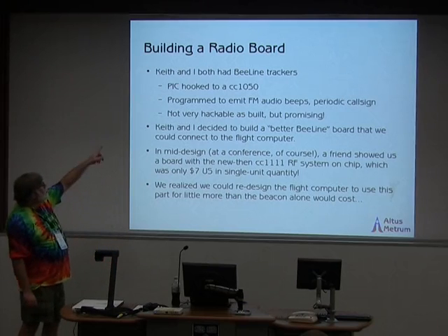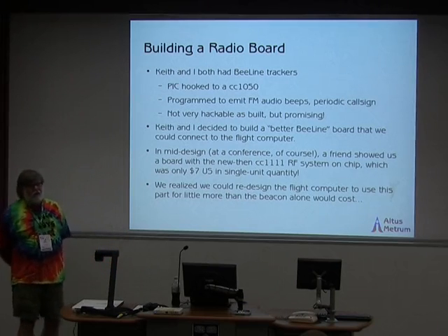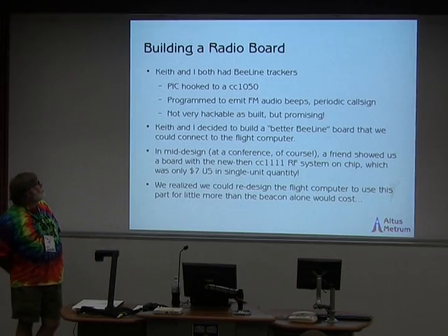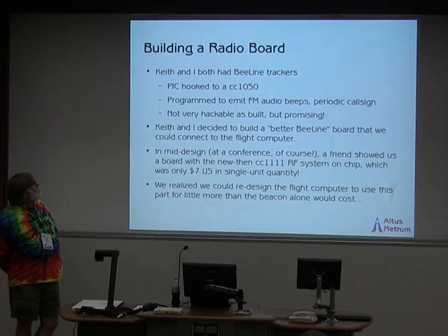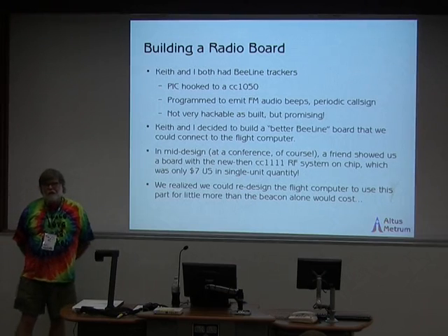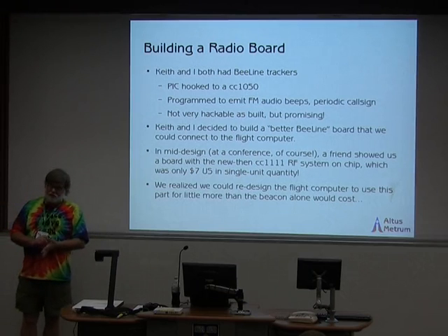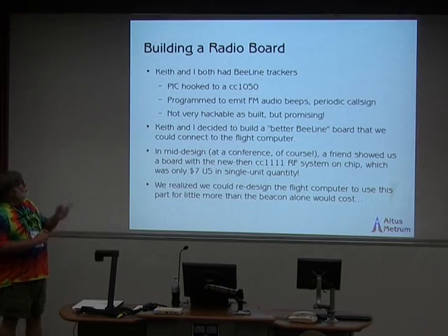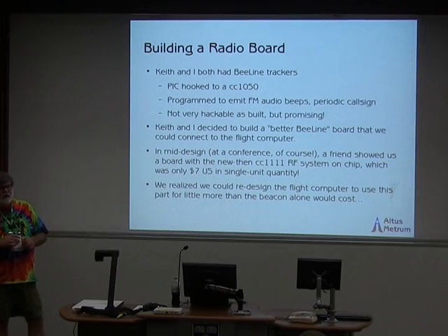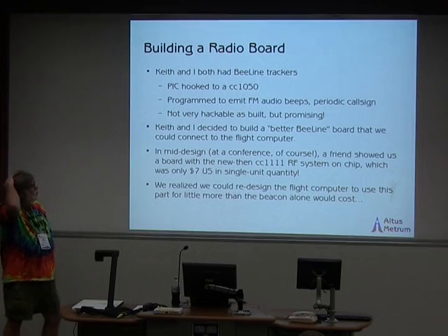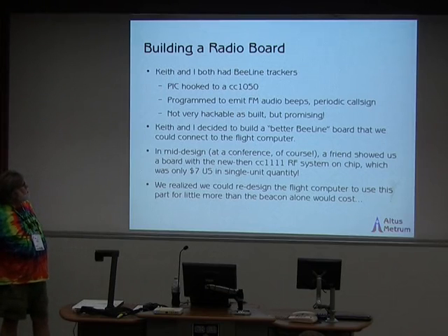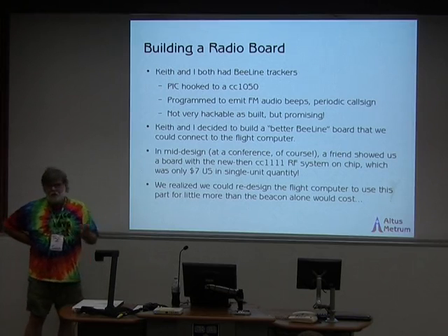board. There's a company in the US called Big Red Bee, run by a mutual friend of ours, that makes some really cool products. One of them that Keith and I both had was called a Beeline, and it was a very cute little circuit board that had a PIC and a TI ChipCon transmitter called the CC1050 on it. The 1050 is a digital transmitter that's meant for use in things like garage door opening systems or something like this. It supports a modest number of modulation schemes, and in any case, in this particular application, it had been programmed to put out FM audio beeps.